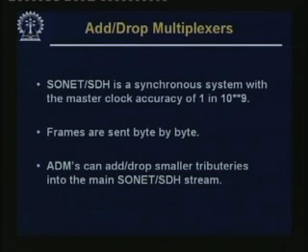Now some of the equipment that we use in SONET, and one of the most important of these is the add drop multiplexers. They are important because at a certain point in the network, there are some sources which want to send into the network. So, there is this SONET equipment, this ADM, let us say, and the SONET stream is flowing like this.